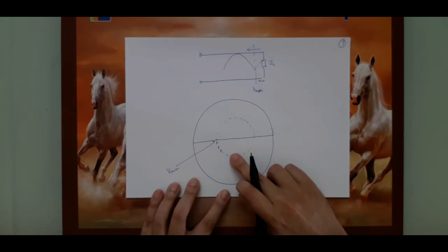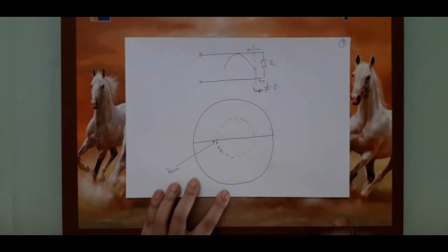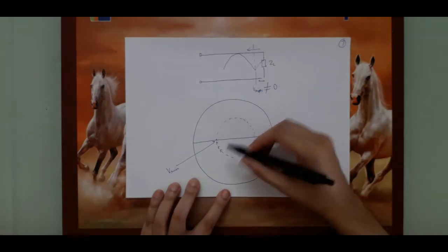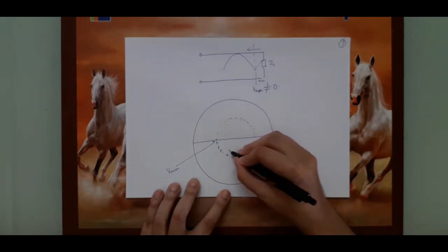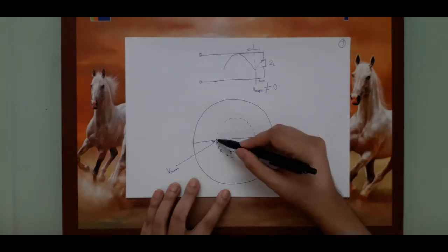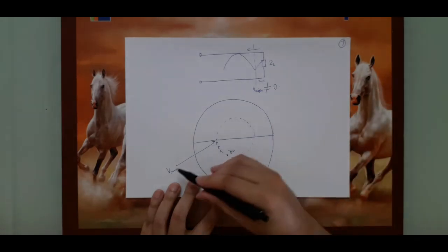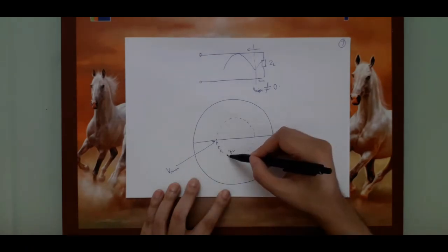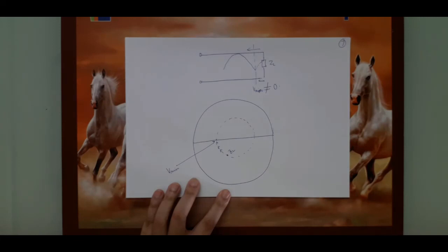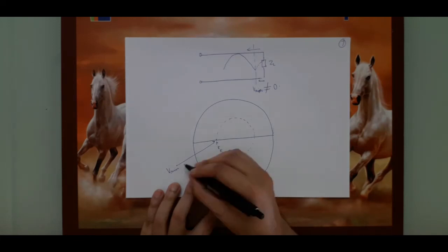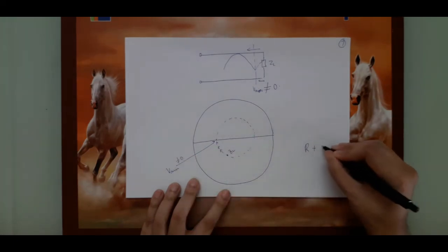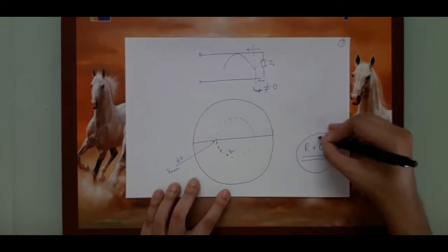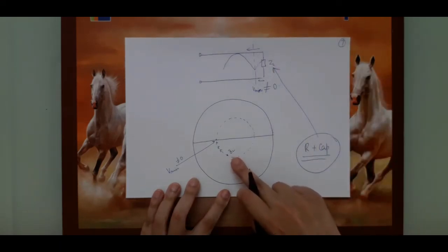We are observing a voltage minima, let us say, which is not equal to 0, some positive or non-zero quantity. So if my load is over here, only then the first extreme point I can encounter is a minima. That will happen only if my load is on the lower part of the VSWR circle. And this voltage minima, as you know, is not 0. So that means this is some resistance plus capacitance. This is it, because we are on the lower half of the Smith chart.